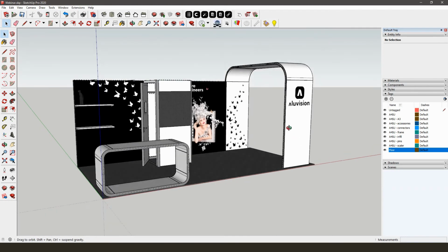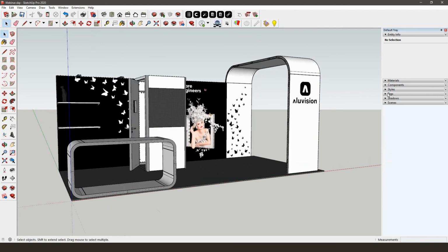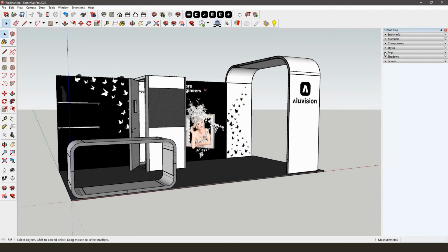In SketchUp, creating scenes will allow you to save different model views and properties, which you can then use to present the model to your own customers. Before you create a scene, choose the right angle and apply the styles, shadows, etc. that you want the scene to display. Also, hide any geometry or deselect any layers that you don't want to be displayed in the view. All these properties are saved in your scene. However, it is possible to update or manage them later on.